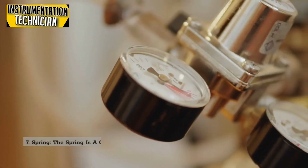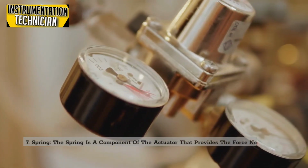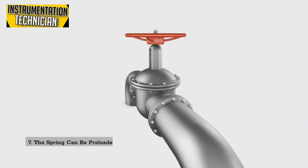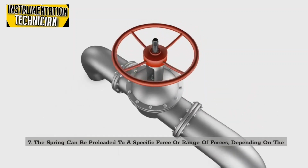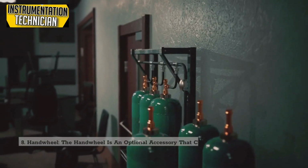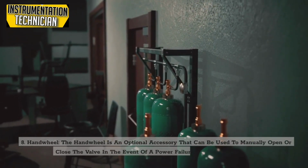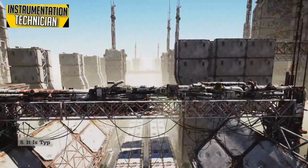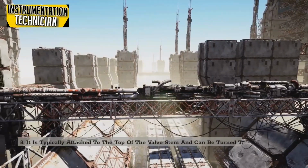7. Spring. The spring is a component of the actuator that provides the force necessary to move the valve plug. The spring can be preloaded to a specific force or range of forces, depending on the process requirements. 8. Handwheel. The handwheel is an optional accessory that can be used to manually open or close the valve in the event of a power failure or other emergency. It is typically attached to the top of the valve stem and can be turned to rotate the valve plug.